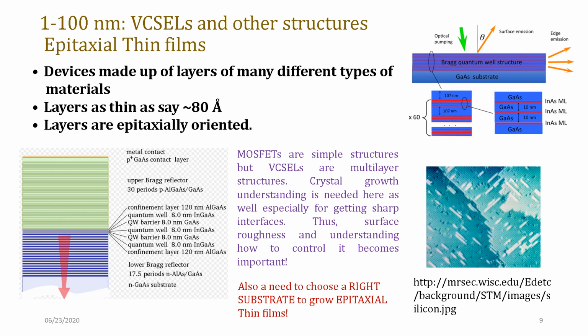And now similarly, if you look at the same feature size, a few nanometer thin films, they can be used in vertical cavity surface emitting lasers. If you know what VCSELs are, that's where we use what are called epitaxial thin films. What are epitaxial thin films? Which means they are oriented thin films in only one particular axis, for which we need to know a little bit about crystal structure, but that doesn't matter now.